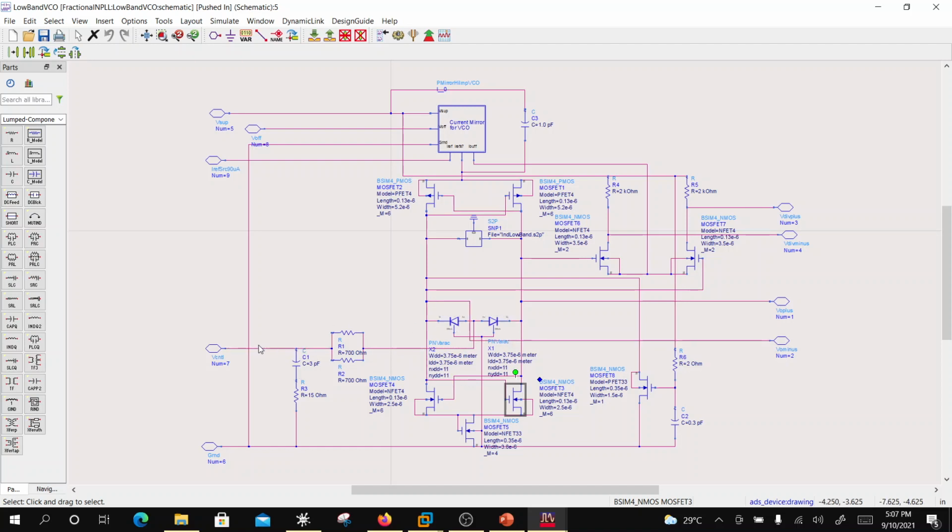If this is directly interfaced to the output of a loop filter, then the loop filter wouldn't build a charge on its output capacitance. It would leak out, right?